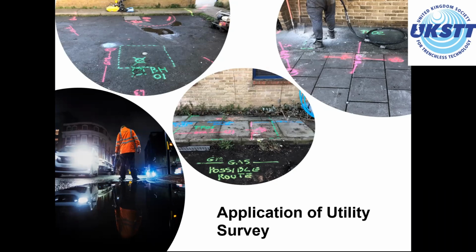We can carry out surveys for load bearing, so we can provide depths of culverts and sewers. With GPR, we can cover the depth of cover for load bearing calculations. A survey can facilitate demolition, so we can locate the services that need to be disconnected or removed. And then as-built surveys, which slightly refers to PAS 256, recording the installation of new assets as they're installed, or surveying said assets that have already been backfilled and covered up.